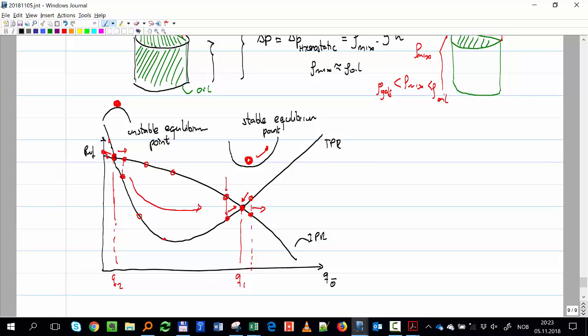That's the tricky part. If you start flowing the well, let's say you stopped for a long time, now you open and you say, I'm going to be rich, I'm going to produce. You're going to reach this point, right? And if you push it to the right somehow, with artificial lift or with something, it will eventually reach that point. But the problem might be that you start your well and it will go back and simply stop.